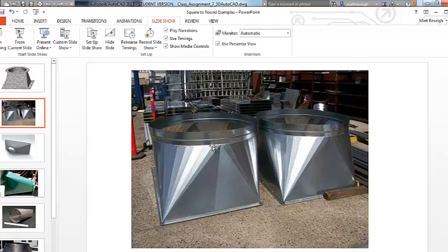So there's a lot of different ways I could do this, but essentially once you've gone transition to round, which is kind of done via press brake work, you can see that the crease lines here have been press broken to the single point down on the base and up to symmetrical increments around the round to make that thing go round. And in front of us here, we're looking at a seam here, and I'm going to get to seams in just a minute and the options I have to do seams.